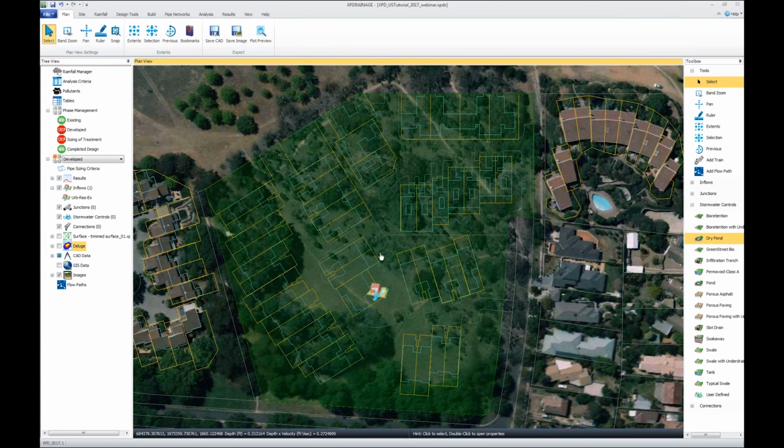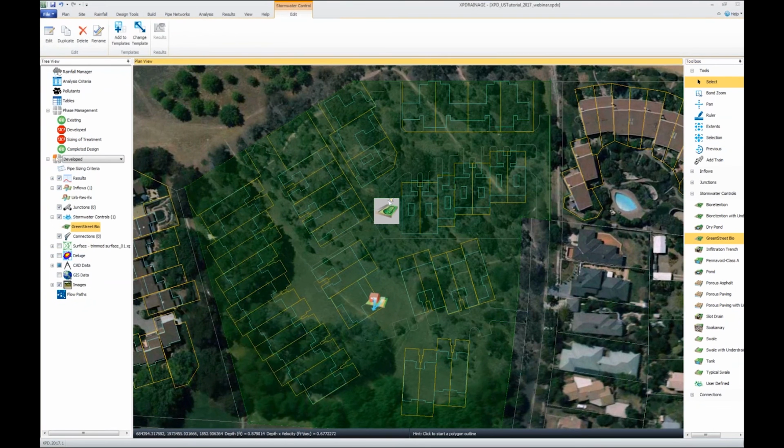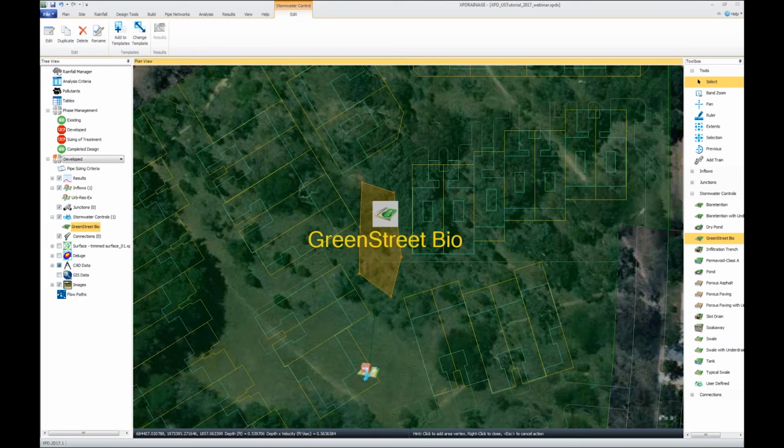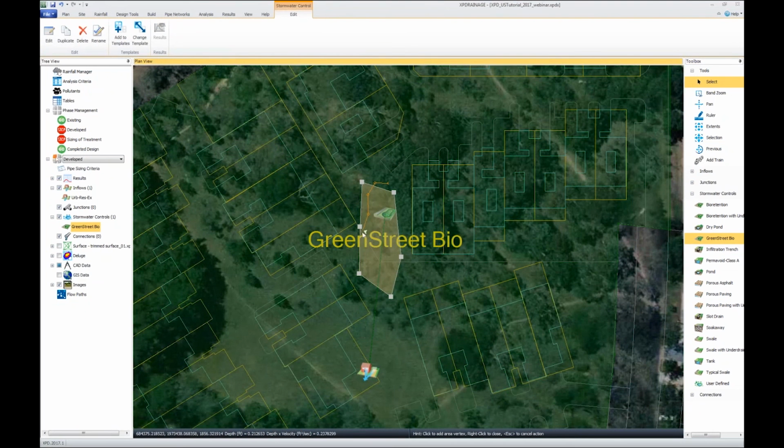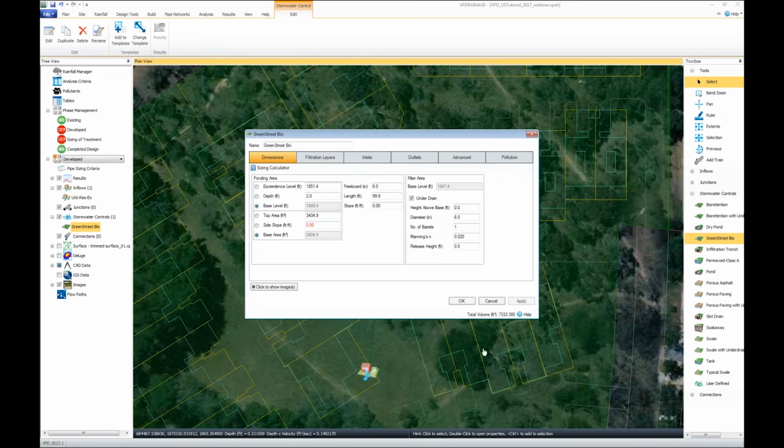Well, I can also draw things to scale and use the elevations in the surface to update my facility. So let's just say I happen to have a rain garden, a bioretention system. I'll add a facility here. Maybe that first outline perhaps wasn't done well enough. You can get as aesthetically minded as you'd like. Great, right? So here's a facility. You'll see my inflow area. It already found that, so let's associate to this. That's this green line. So what did I just draw?